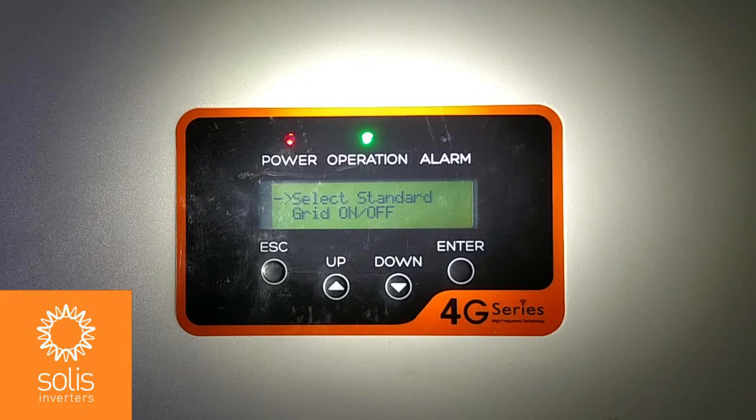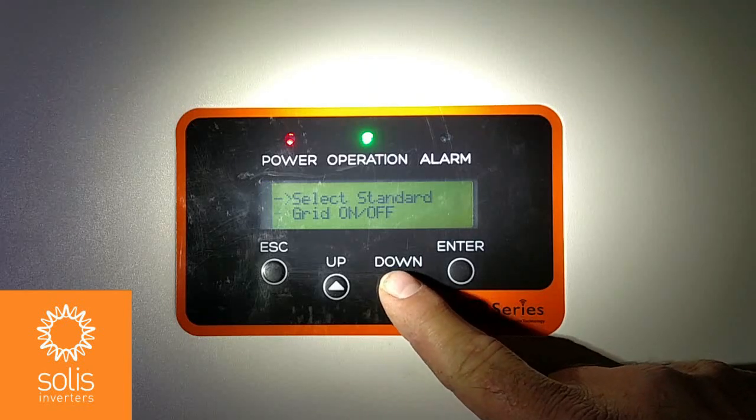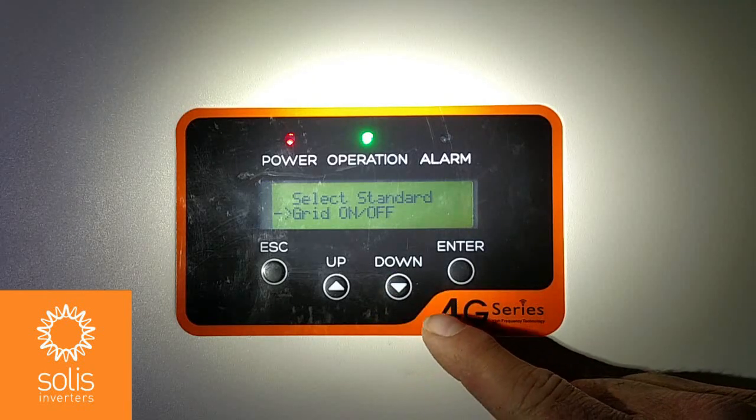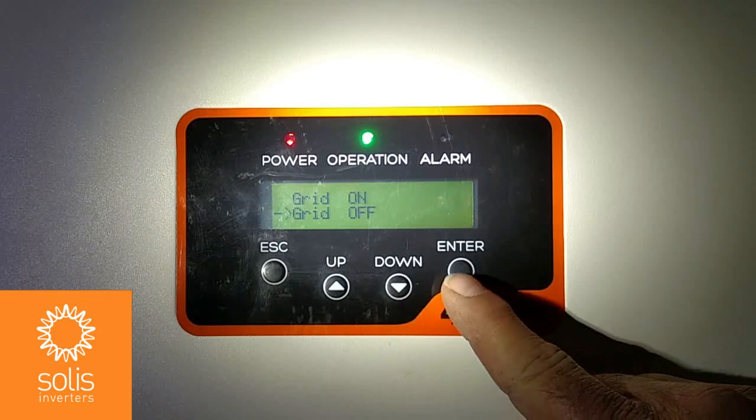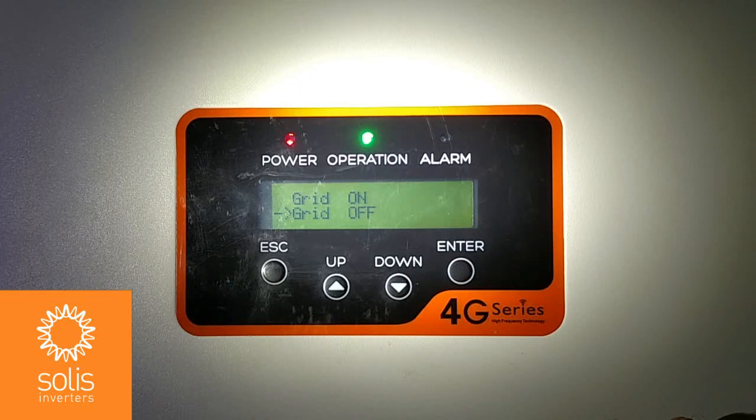Okay, so now you can see you have 2 choices here. We're going to again use the down arrow key to move to grid on off, enter that menu, move down to grid off, and press enter. The inverter will now cycle. You'll see the operation light go off, and you may see the alarm light come on indicating that there's no grid. However, what we need to do now is select the standard.